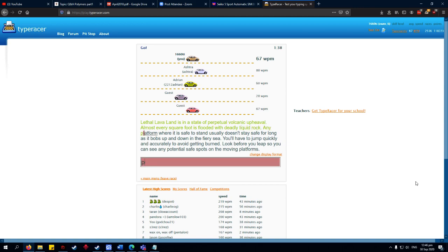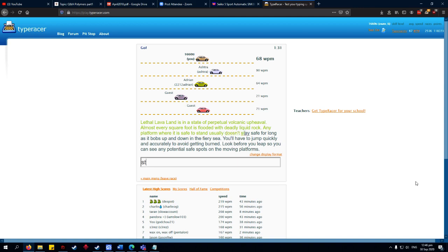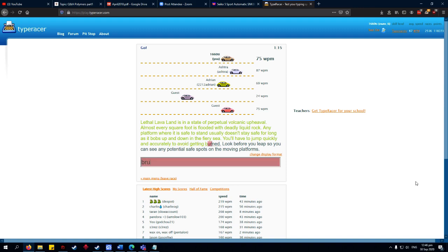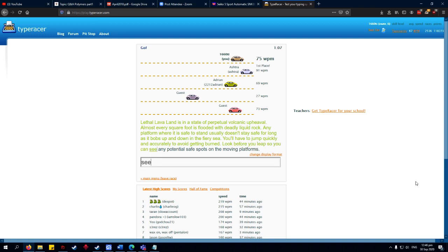For small values, if you write 0.97 ampere for 0.965, your succeeding calculations will be far from the exact value. So it is better, for currents, to use microampere or milliampere so that you will be able to get more significant digits.